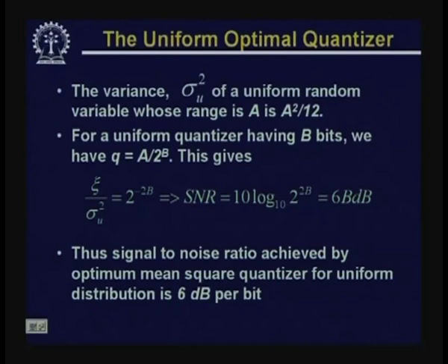That means, if you increase the number of bits by 1, the number of quantization levels will be increased by a factor of 2. In that case, you gain 6 dB in the signal to noise ratio in the reconstructed signal.